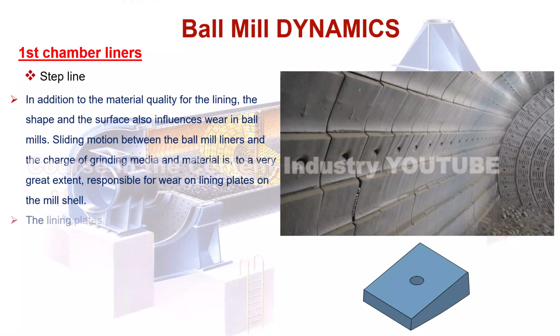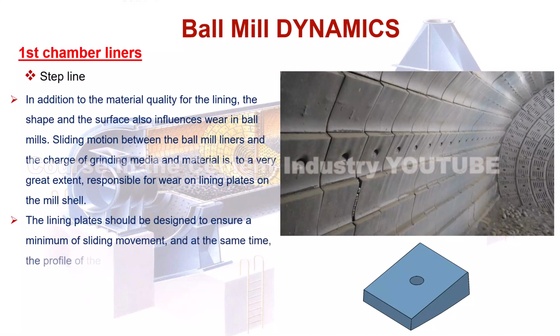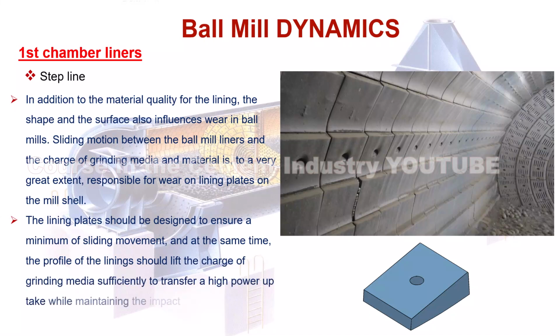The lining plates should be designed to ensure a minimum of sliding movement, and at the same time, the profile of the linings should lift the charge of grinding media sufficiently to transfer a high power uptake while maintaining the impact forces at an acceptable level.